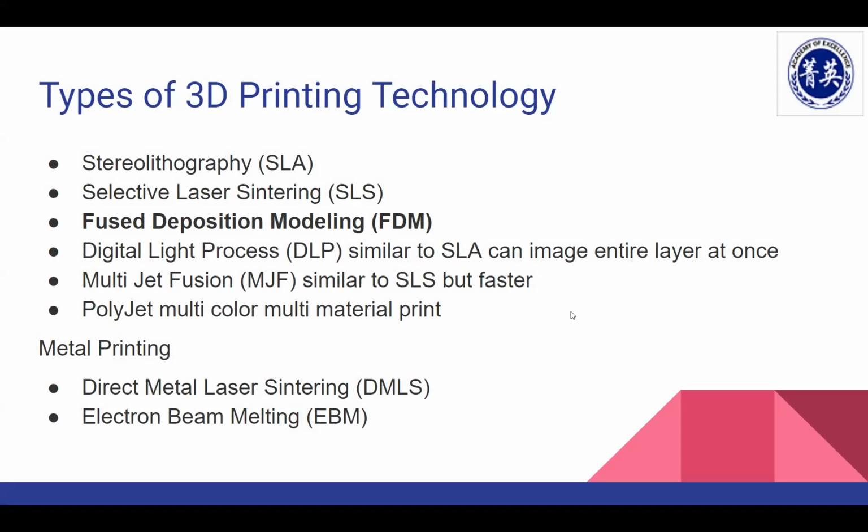Now we mentioned industrial. Well, to understand 3D printing, there are a few different types. SLA, which stands for stereolithography, is basically resin-based 3D printing. You have a laser that runs over a pool of resin that sits on a building bed. The laser hardens the resin layer by layer and the bed moves down, right? So it's very similar to the filament printer we just saw in the video a minute ago.